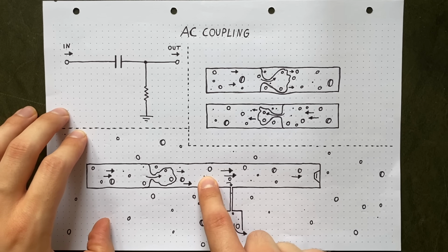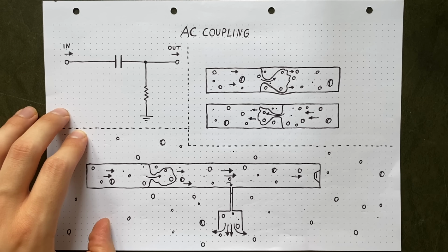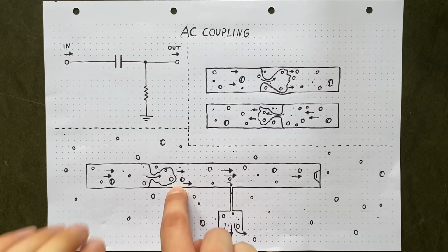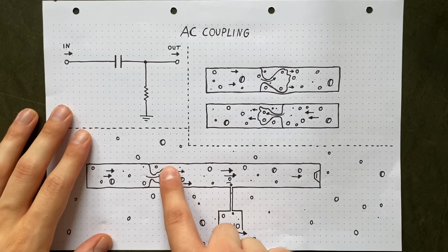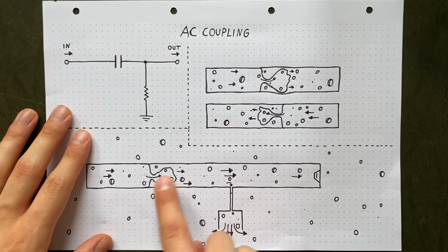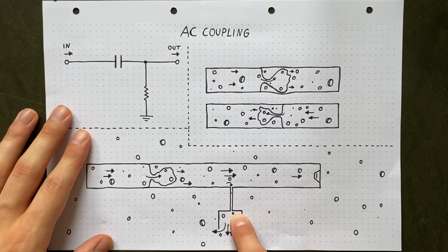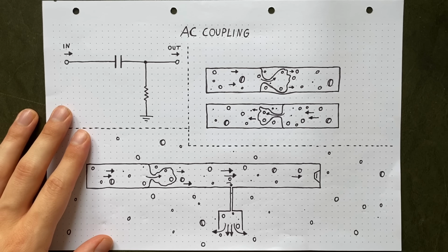Then on this side, we'll read 0 volts after a short amount of time. Why? Well, we are pushing water into the balloon with a constant force from here. The balloon is stretching into this pipe, pushing water in this direction. If we didn't have the equalizing valve here, there'd be nowhere to go for that water. But since we do have it, the excess water can drain out through this narrow pipe, out of the system, until the pressure is neutralized and no water is actively flowing anymore.